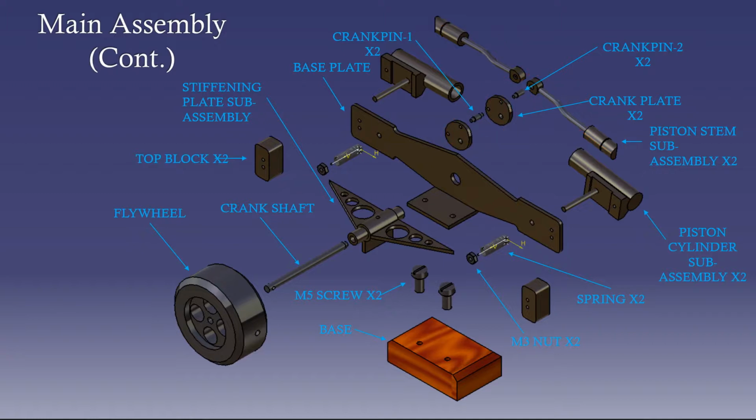Another quirk about this part were the holes in the base wood block part. In the dimension drawings, these have no dimensions because they are merely pilot holes for 2 screws of any dimension to fit inside of them. When modeling the base plate, I decided to go with a diameter of M5. This in turn led me to select these 2 screws from the CATIA part catalog, and that's basically it. The same can be said for these nut pieces right here.